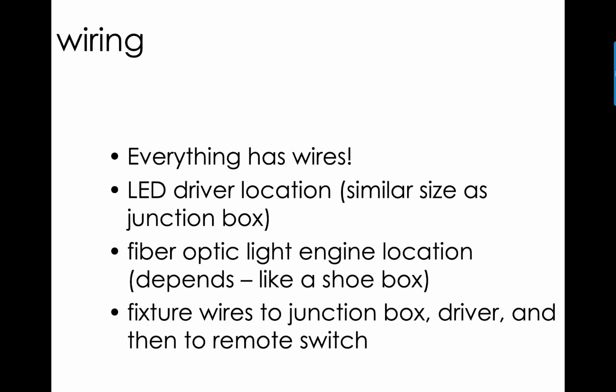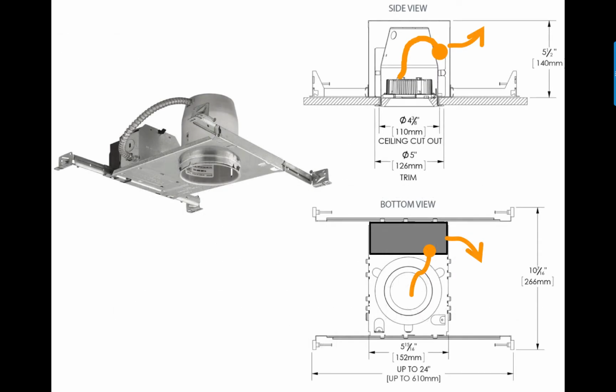For LEDs, there is a driver. So even if you have some totally custom, funky shaped light fixture, you do have to have a driver somewhere, typically up in the junction box or around the junction box. So, let's just take a look at some standard fixtures to see how they're wired.